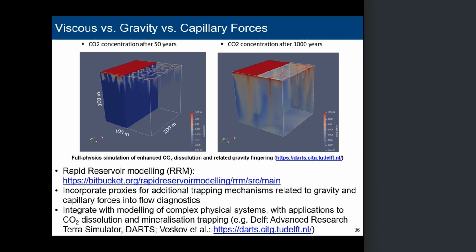Is there a limitation on the number of grid cells, say up to a million? The limitation is the amount of memory your PC has. This afternoon the students will have laptops and run it on those. They had 100 grid cells in X, 100 in Y, and 100 in Z, and for that resolution the calculations run in 2 to 3 seconds. Depending on how good your computer is, you can add a bit more, but probably not an order of magnitude more before things become slow and you potentially run out of memory.